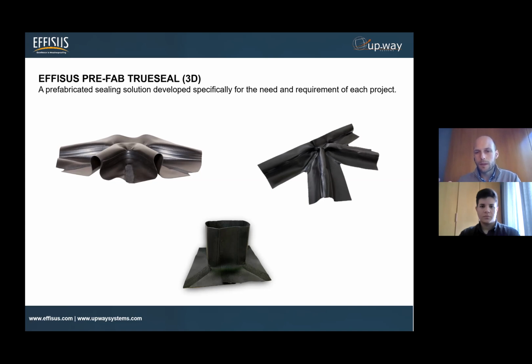The performance of the EPDM is something that until now cannot be matched by other solutions. So here we are taking advantage of the EPDM and making tailor-made pieces. We have the technology to do so without any leakage points, with hot vulcanization, without any glue. This is EPDM with EPDM, vulcanized at the factory.